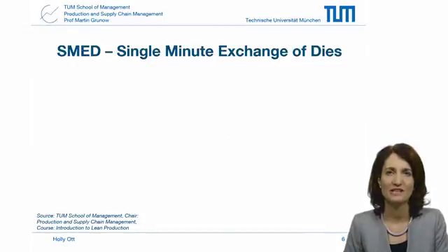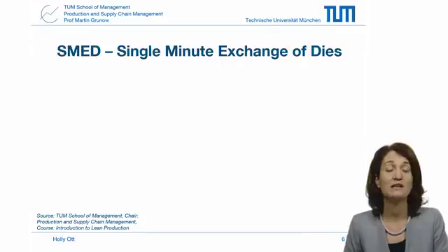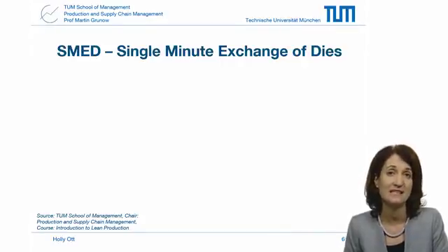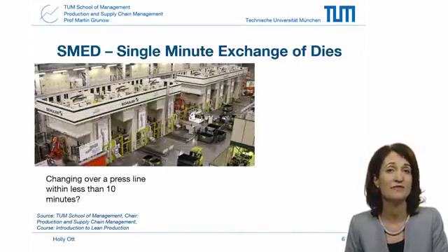Setup time reduction techniques are often referred to as SMED, which stands for Single Minute Exchange of Die, from the classic work by Shigeo Shingo at Toyota. And he didn't actually mean single minute, but that changeovers should be roughly less than 10 minutes. But why is this so difficult? Why can't changeovers be fast?